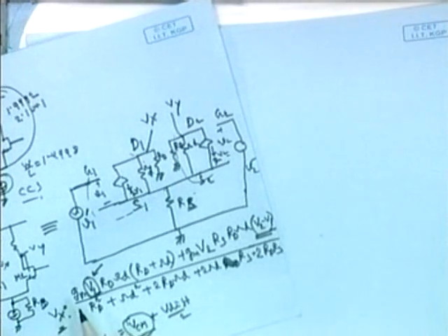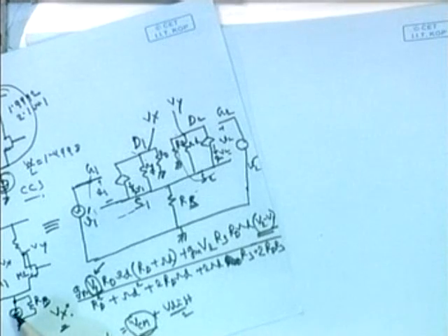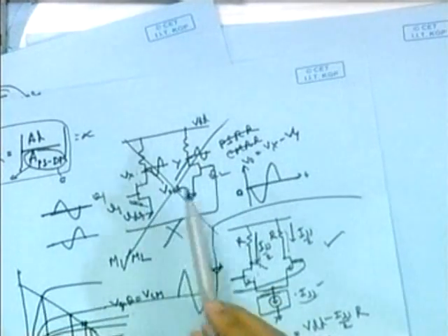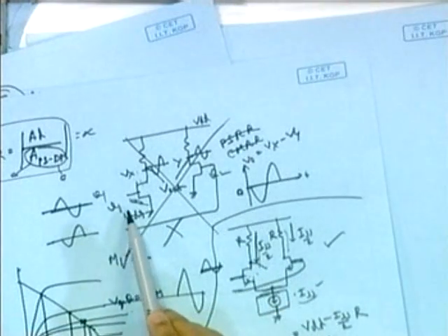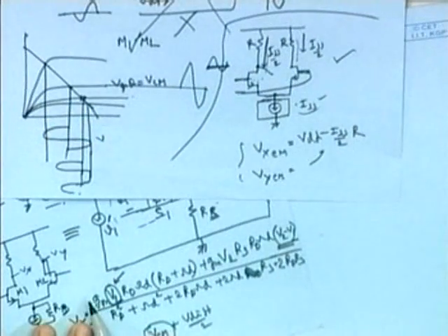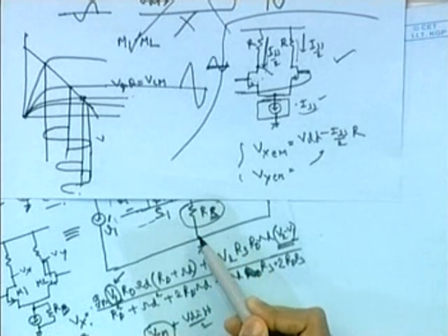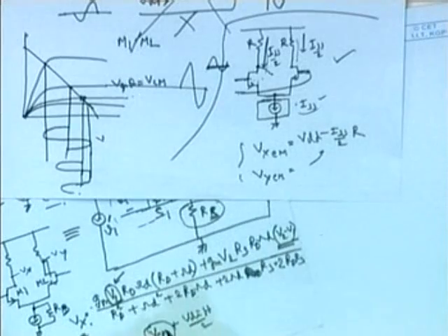So the whole purpose of this constant current source is getting invalid here, because in our previous circuit we are getting directly the input CM in the output. Here also we are getting some fraction of this. Why fraction? This factor will be there, GM RD multiplied with and divided by this fraction. This factor into V2 or VCM is coming at the output. So the effect of this finite resistance is to make output a dependent of input CM.